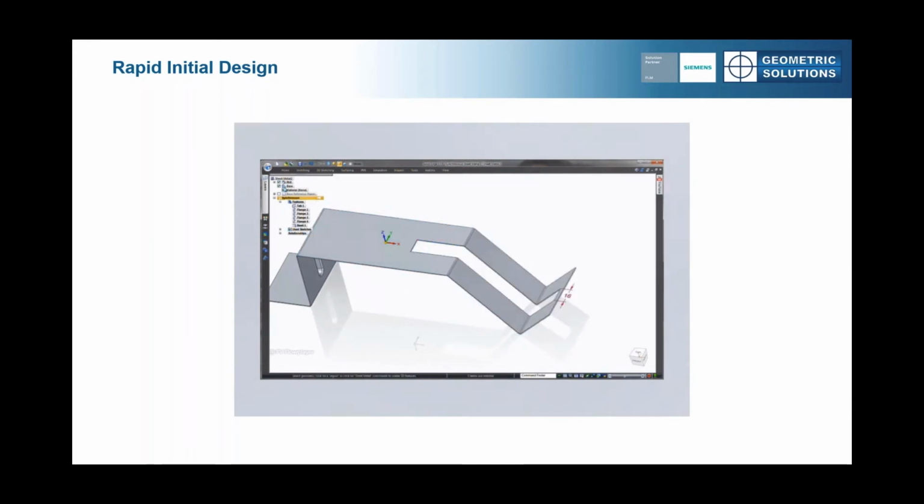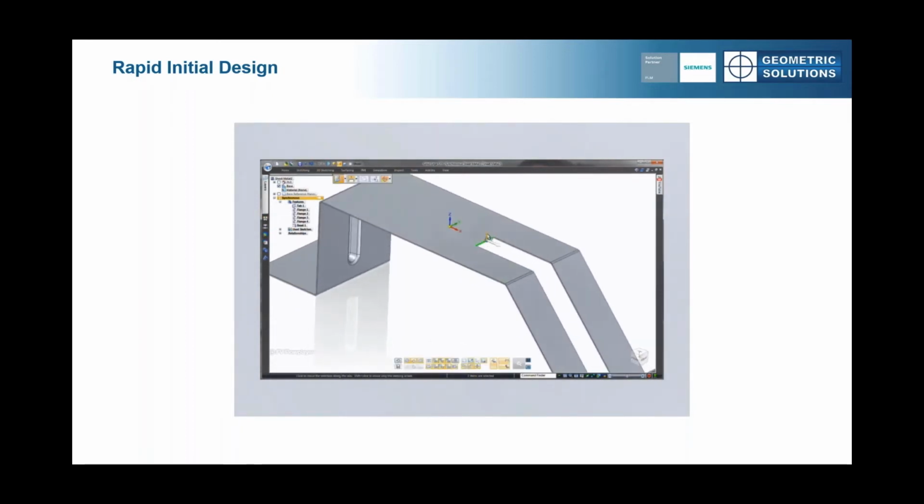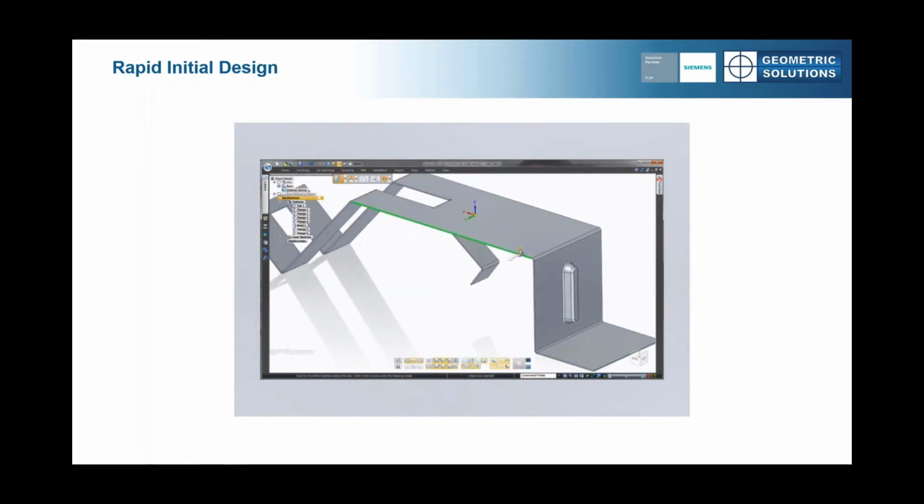Very nice. For the retaining clip that we need, let's drag out a couple of flanges here and angle them both in. Same process as before, pull to create, and then the steering wheel to angle. We also need a sidewall to contain the connector block, so let's add another flange. But the material needs to be on the inside and a partial flange, not a full. Great.